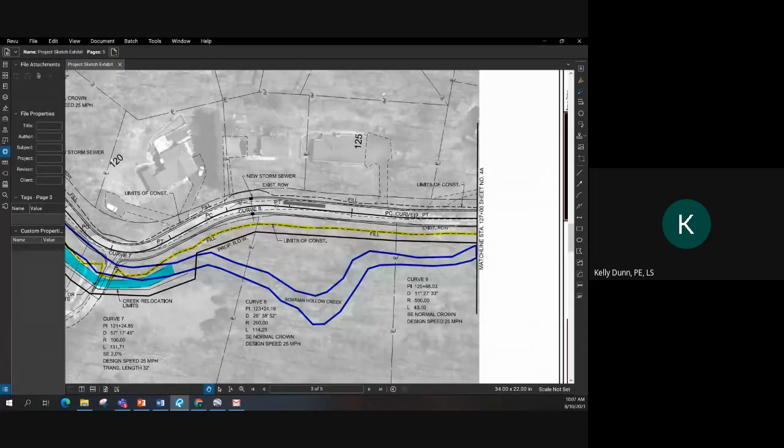Let's see, based upon the sketch and lack of detailed line item cost estimate, we were unable to determine if erosion and sediment control measures were included in the estimate. The limits of driveway connections don't appear to be considered in the estimate sketch, but should also be considered.